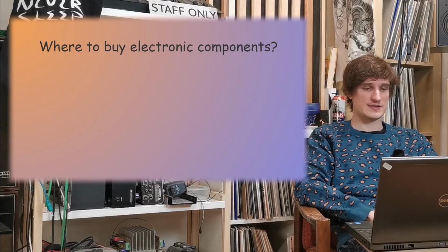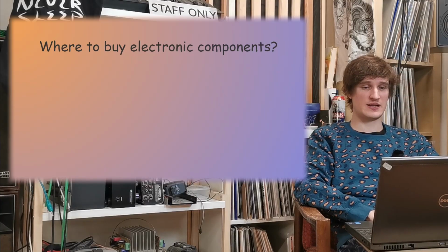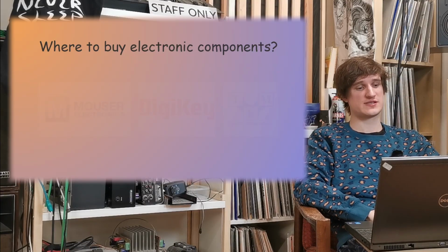On internet forums you can find some research on this, where someone scraped off the tops of two op-amps, original and fake, and analyzed the internal structure, and it was very obvious which chips were fake, and unfortunately the fake chips had worse performance. So I recommend buying electronic components from official sources.